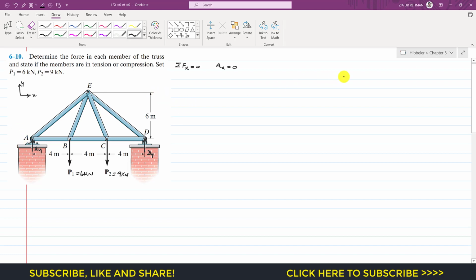Similarly, if we apply the summation of moment about point A equals to 0. We can see that this DY is producing the counterclockwise moment about that point A. So I will write DY, and the counterclockwise moment is positive, and the moment arm of this DY from that point A is 4 plus 4 plus 4, so it is 12. So I have to multiply it with 12.